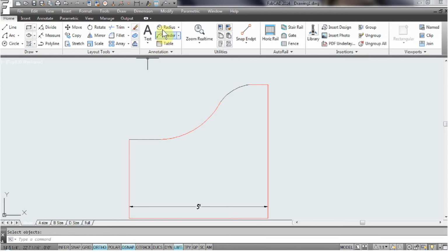And then we'll do the bottom. So let's see what the radius is for that first. Radius is 2.6 7/16. That's close, but not close enough. So we'll erase it. And we'll do start, end, radius again. We'll start from the bottom up because the other one bowed this way. The other one was going to bow down. Start, end, and that's 2.7.